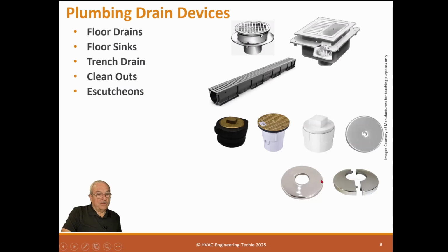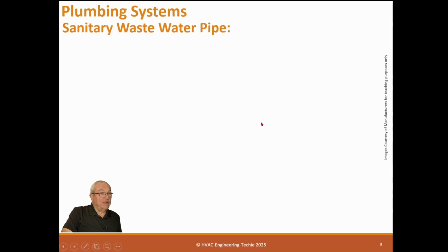And then there's escutcheons, and these of course go around pipe. This is a split escutcheon. This one is not, so this has to go on before you finish the pipe. This one goes on afterwards, so you use whichever one you have to, to make it look pretty.